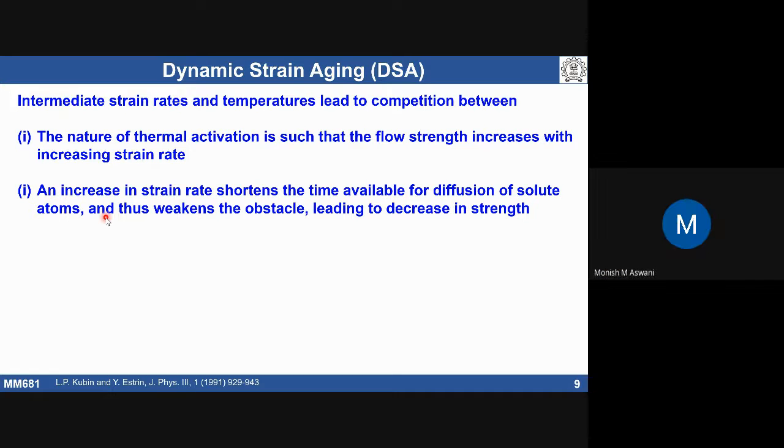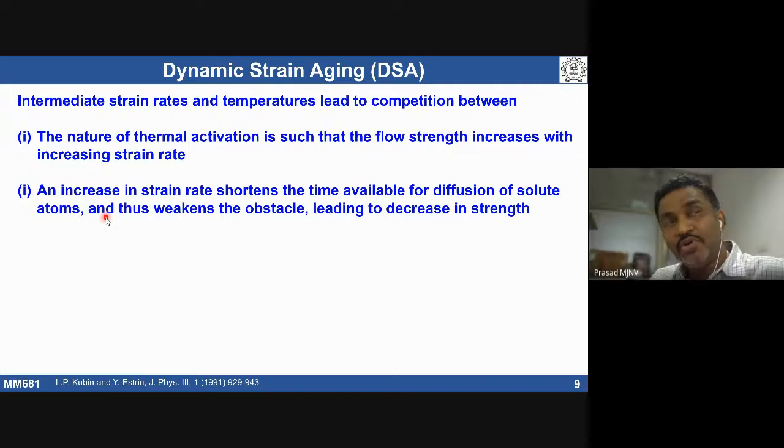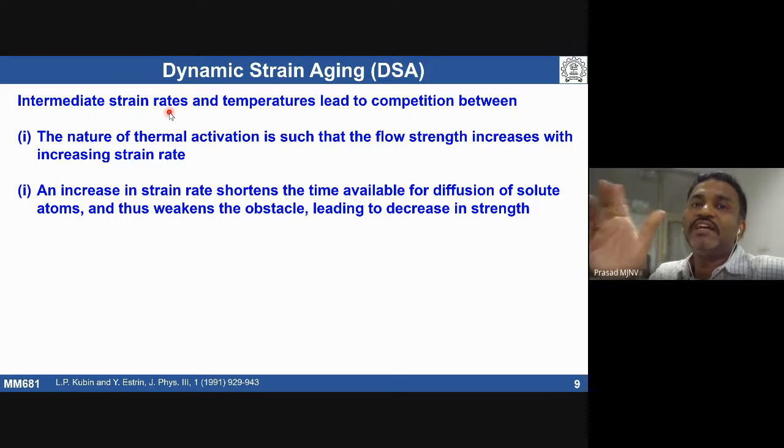So if you're just increasing the time and not increasing the temperature, then there'll only be that increase in stress, right? You won't see a decrease in stress because you're not increasing the temperature. No, no, right? See, we are talking at a particular temperature. Okay, that's what I said. There is always a window of strain rate and temperature. The combination of strain rate and temperature is going to vary.